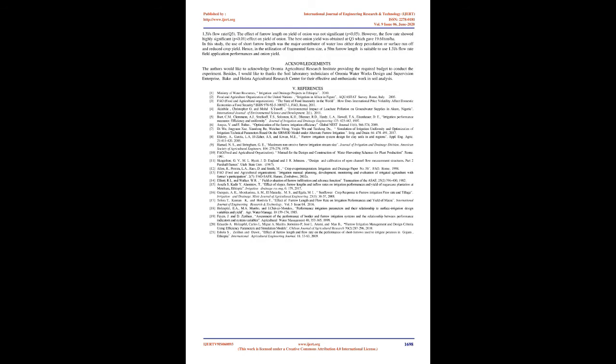p<0.01. The best result of 65.87% was achieved for the treatment combination of 1.3 L/s flow rate, Q3, and 25 m furrow length, F1, and the least, 53.6%, for the treatment combination of 0.7 L/s, Q1, and 50 m furrow length, F3. The effects of furrow length and flow rate on storage efficiency were highly significant, p<0.01.